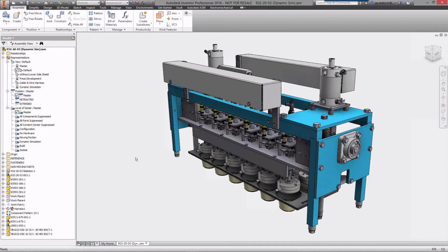And these have a thermocouple which is inserted into the side. You can see it right here. It's just a placeholder for the thermocouple itself. So what it does is it actually superheats the air that is underneath the foil cap, and the foil cap stretches as the heated air expands, and that is how they detect whether or not the foil cap or the foil lid is in place.